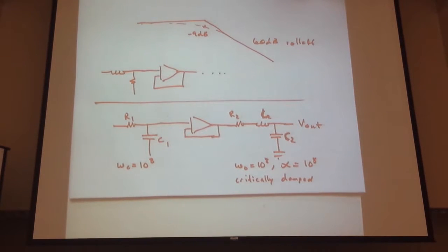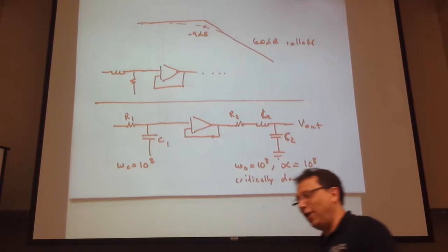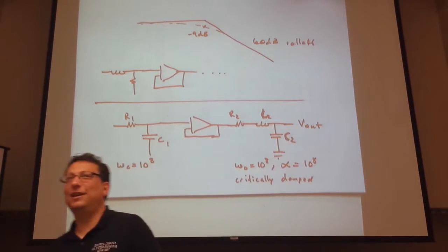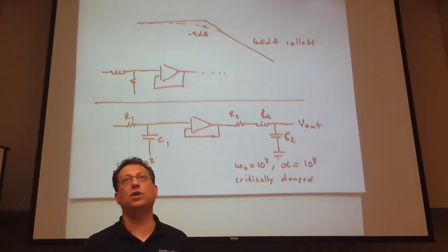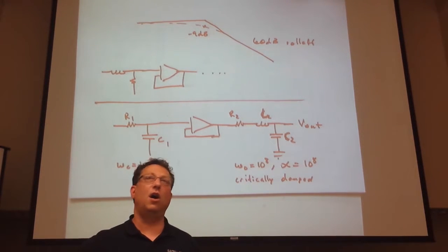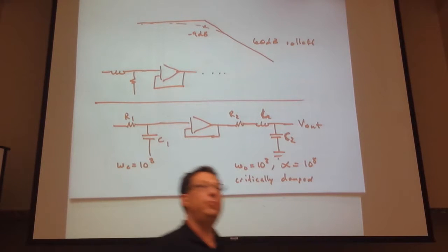Well, one thing to point out here, how many constraint equations do I have here? There's one. So what happens? I have two unknowns. How do I start with the design process? Maybe I should have mentioned this earlier. Make R equals 1. Yeah. That's probably not the best choice, but you pick one. Doesn't even matter which one you pick. You can pick the R, you can pick the C, you pick a value.